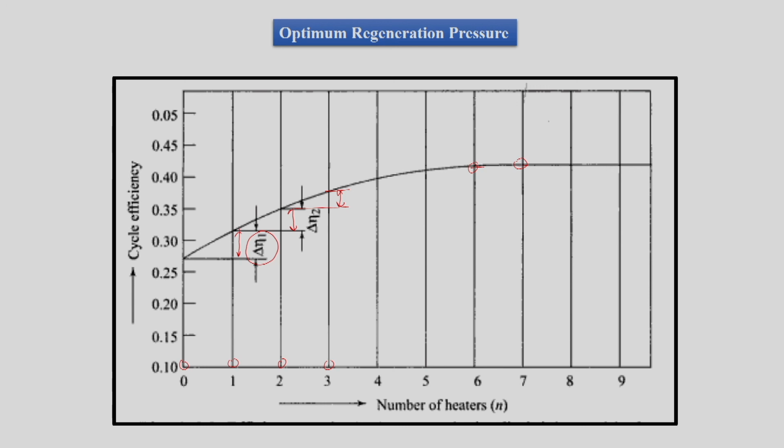So, this is how we end our discussion on the process of regeneration, where we have seen how to implement the regeneration process in a steam power cycle, where we can improve the efficiency and implement different types of feed water heating systems, where we have closed type of feed water system and open type of feed water system. We have seen that if we are going to do only electricity generation, then there are certain cases, but if we are going to do cogeneration or process heating, then how regeneration comes into the picture for the back pressure turbine or also for the bypass turbine.